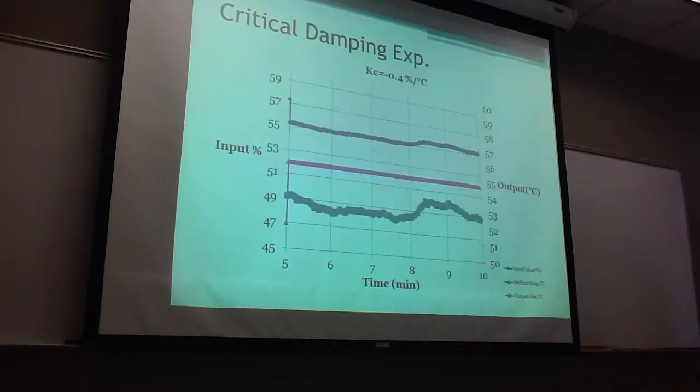And for the experiment, we had a fun time. We ran it like 30 times, literally 30 times, and we kept getting different values trying to find the set point. So I just arbitrarily picked one based off of the SSOC graph. I chose the M bar to be 55%, which made the set point 47 degrees Celsius. We just went with that, just so I'd have something to show you.